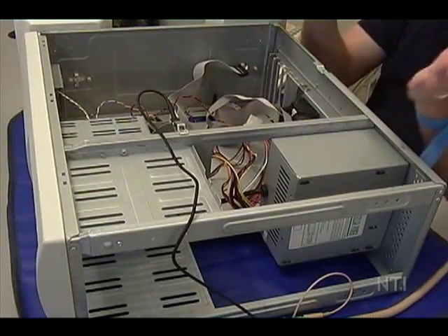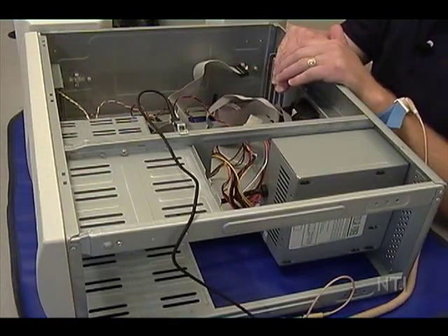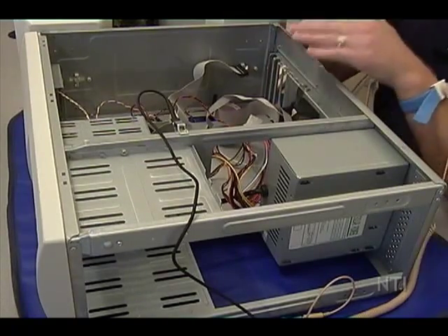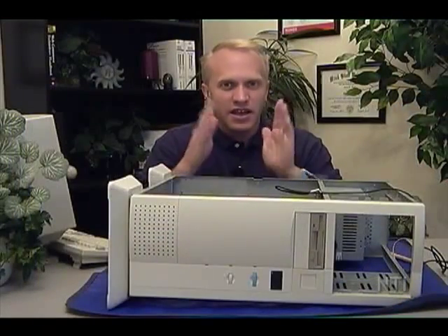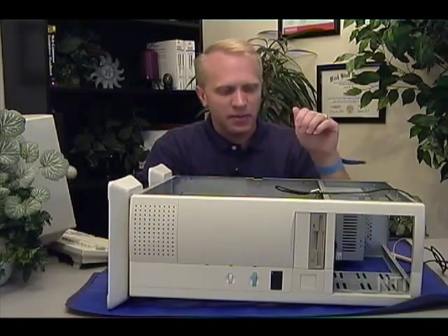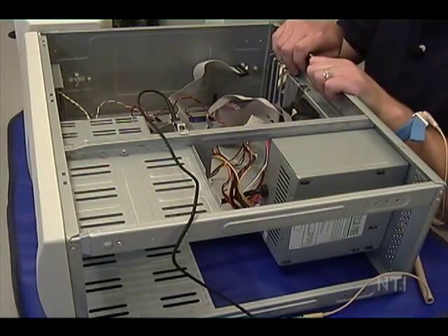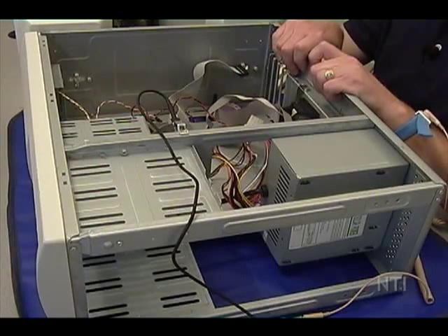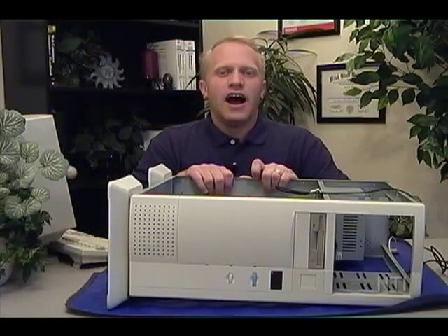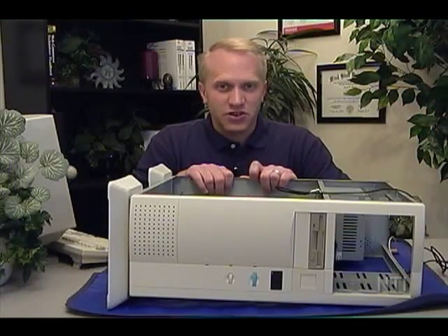At this point, I am now grounded to this computer, and there can be no static charge build up on either side of it because we're always dissipating our charge between each other through the mat. Now the question arises then, whether or not I should have this computer case plugged in while I'm working on it. There'll be those who will argue that you should because it creates a perfect ground. I disagree, and the CompTIA folks disagree as well.